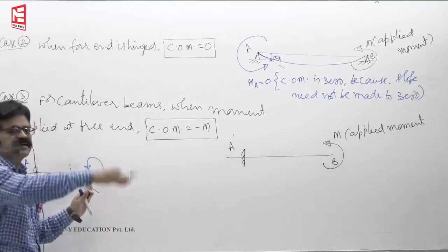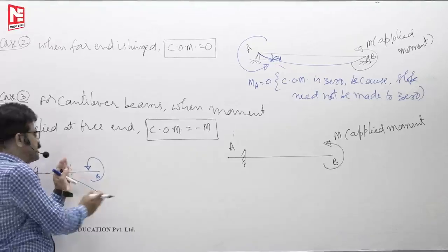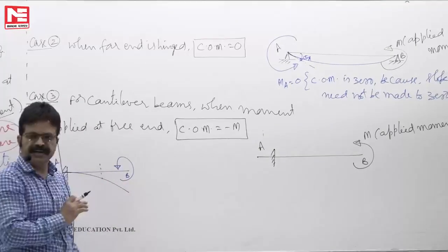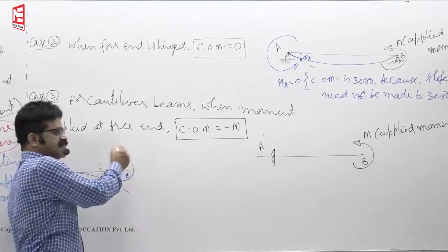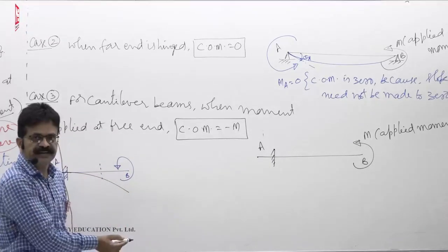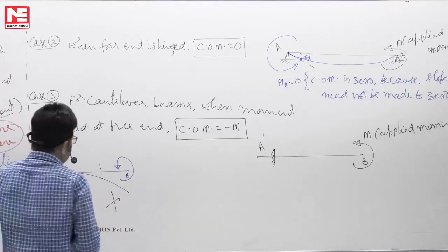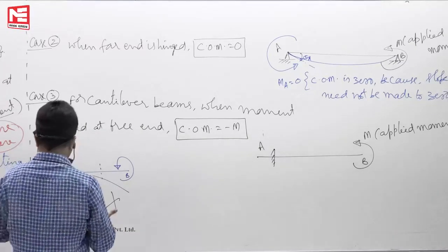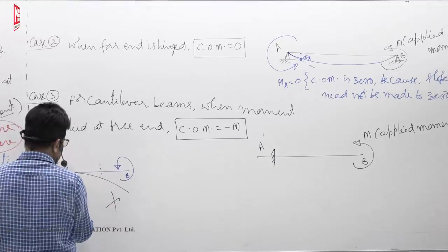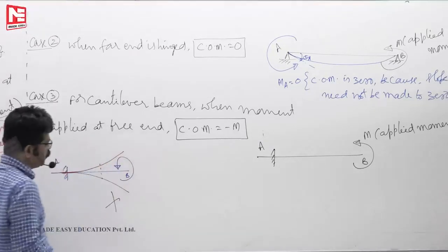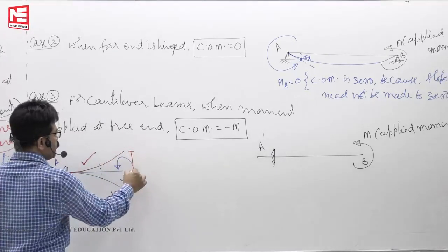Now check. Stand here. Section right side anti-clockwise. Will it sag or hog? Section right side anti-clockwise moment is a sagging bending moment. That's what we have studied. So once we are saying that it is a sagging moment, but you are showing hogging, that means it is wrong. So how will it deflect? When you apply moment M like this, it will sag. For it to sag, it should go up only. Now this is a sagging moment, so deflection is now upward.